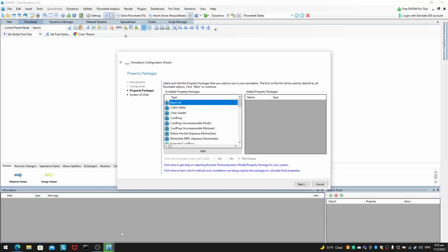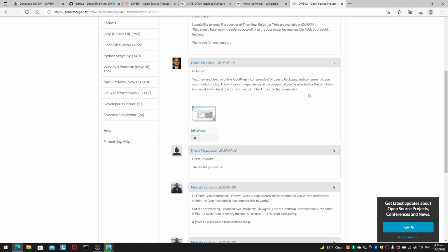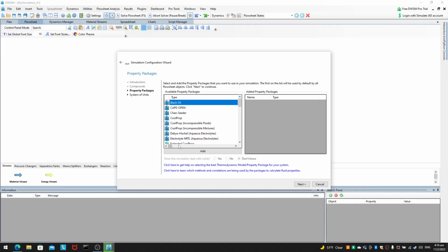So what he's saying here is that the compounds that we selected just now, even if it's not the full Therminol, well, the closest thing I got is biphenyl, because that's one of the components of Therminol. Since that is the closest thing, I just selected that, but any fluid will be okay. For this video, I just select that, and I use the CoolProp incompressible fluids thing, and then you have to add, and of course you have to configure it to use Therminol VP1.